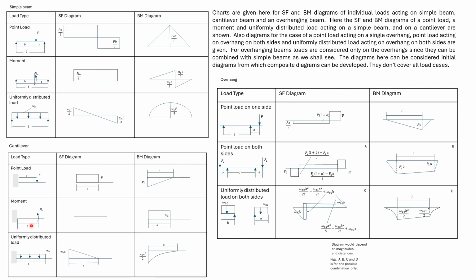Here we have a moment acting on a cantilever. It will cause no shear force. If the moment acts at a distance a, then the moment diagram will have a constant moment for that distance.